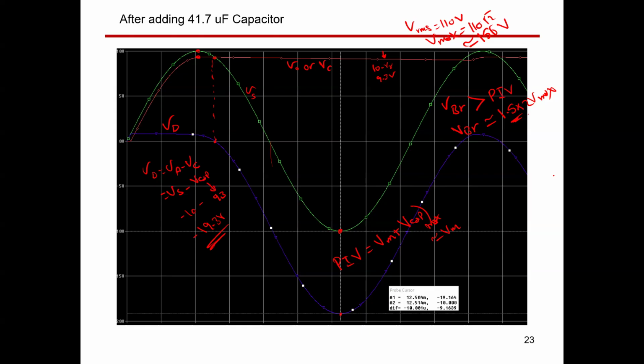So in this case, we may select a 450 volt or 500 volt diode in order to support the maximum peak reverse volt you have in your circuit. Okay, guys. So now, for the rectifier circuit with the capacitor, we made sizing for two parameters: the capacitor as a filter and the diode as the main rectifier element. Okay, nice. Very good.